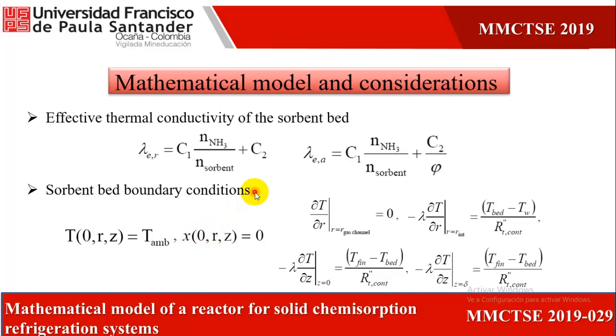That is to say that at the beginning of the system no refrigerant is absorbed, and in radial conditions we observe that we consider a constant resistance, and in the axial direction here, it was considered that the adsorbent bed between two fins has two constant resistances also considered.